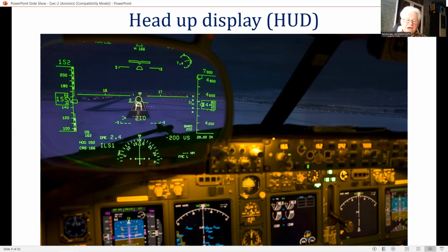Or enhanced vision, using a raster mode HUD to project a clear video picture of the outside world from the FLIR sensor installed in the aircraft, or a synthetic picture of the outside world generated from a forward-looking millimetric radar sensor in the aircraft.